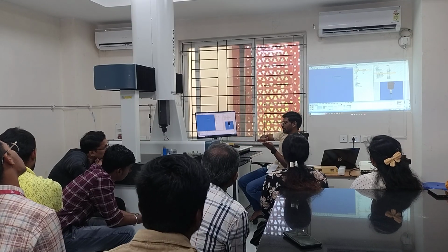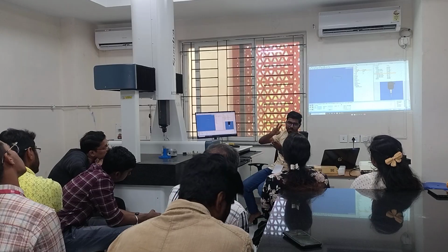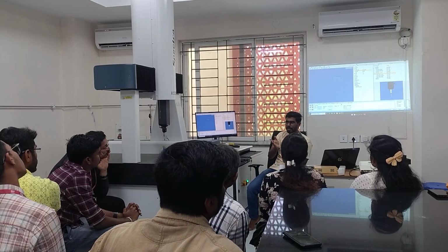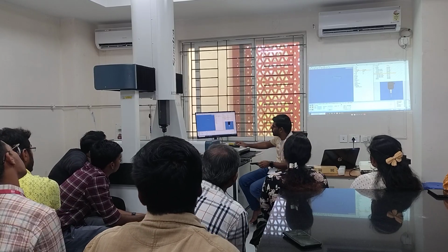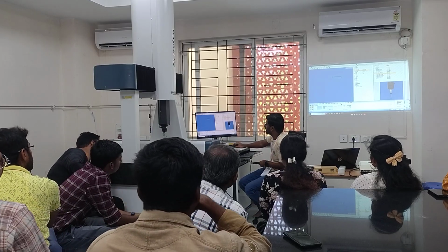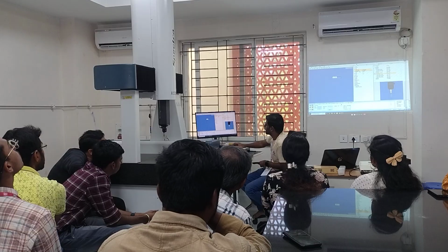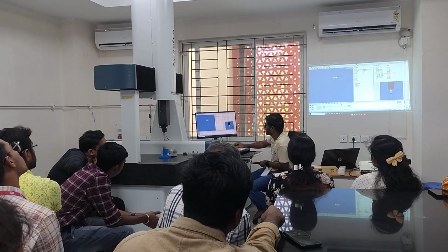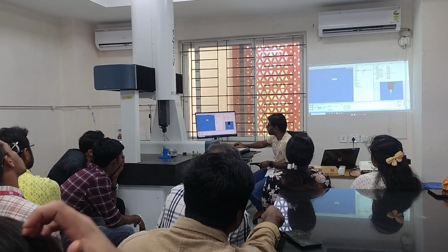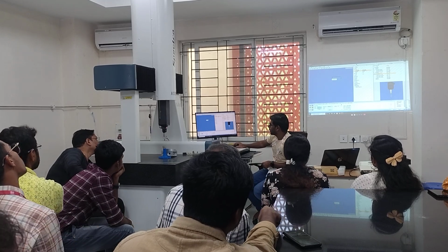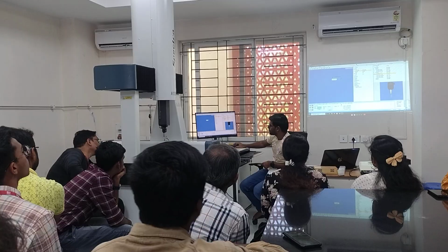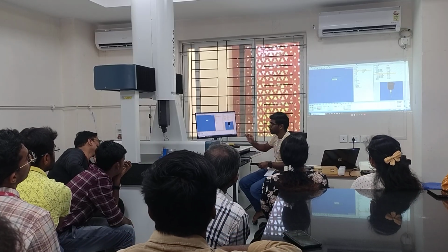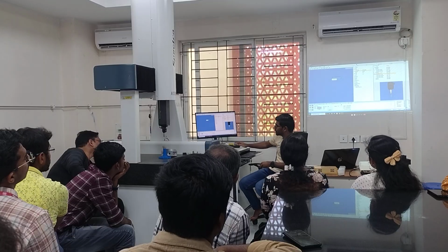So for inclination, there must always be two features required for an angle, right? If you want to measure any angle, there must be two features, or two lines or two planes or something, because only then you'll be able to compare. So one, I'll keep as the top plane, I'll take the actual one. Second one is the inclined plane. I'll put it. Then nominal, it should be 50 degrees. Nominal means exactly how much it is in the drawing. It must be 50 degrees.